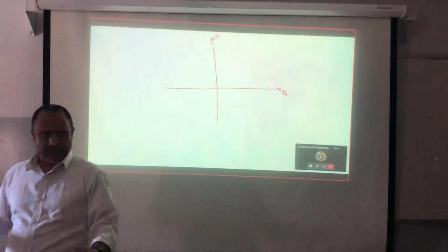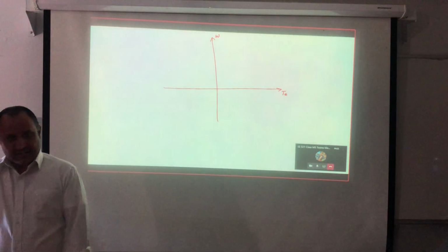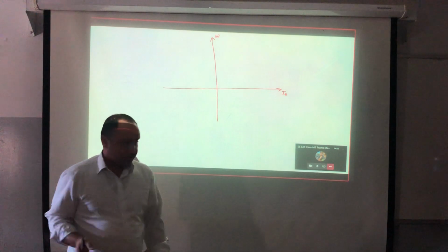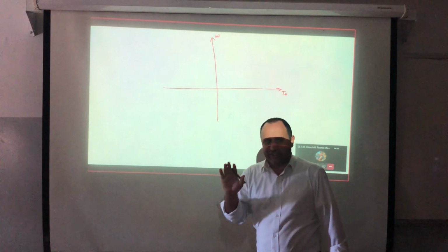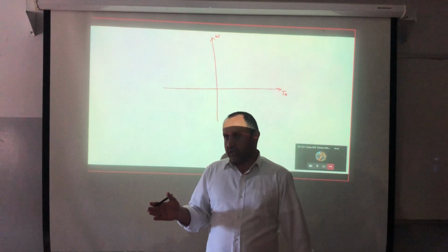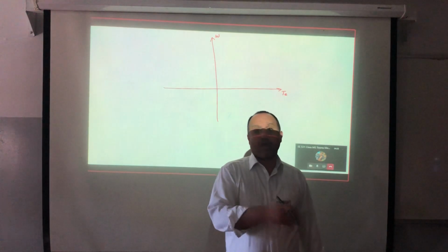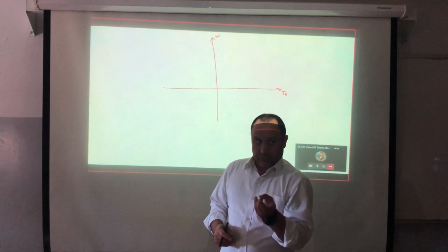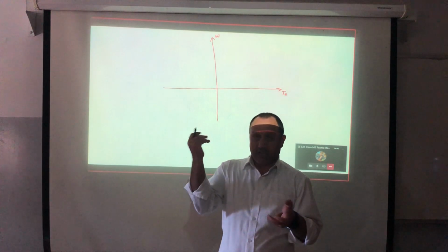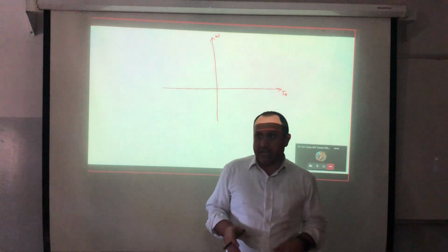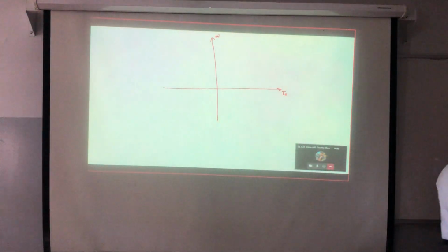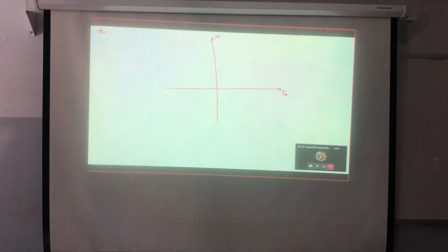Any rotating system can rotate either clockwise or counterclockwise, so there is no meaning for plus and minus. As engineers, we use the plus and the minus as the sense of direction. And if I need to discuss the mode of operation, I must fix the field direction. Otherwise, I cannot say the motor is rotating clockwise or counterclockwise, because if I exchange the direction of the flux, it will rotate in the other direction. So here I will discuss with you the mode of operation.